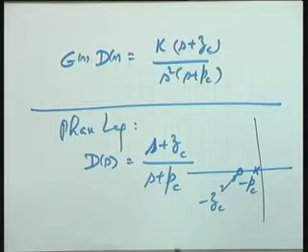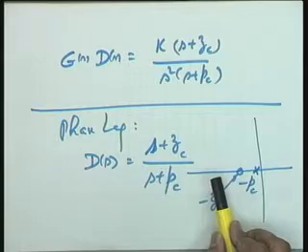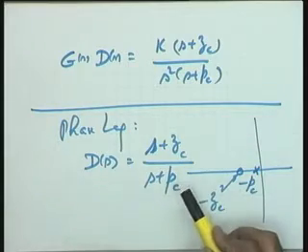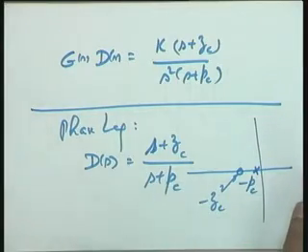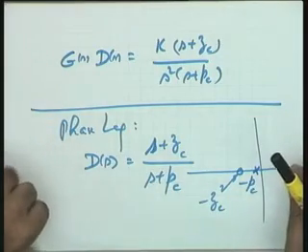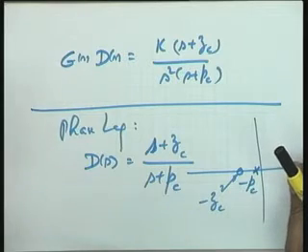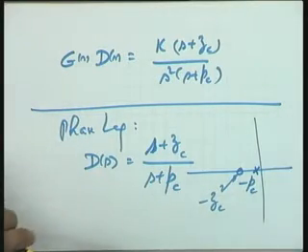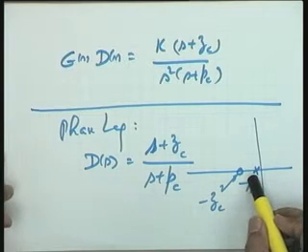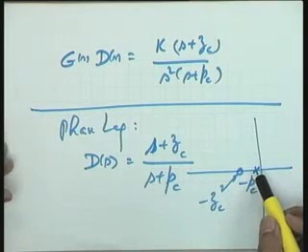Okay, so this is again a pole-zero pair, as you find, with a pole near the origin and a zero following there, and the ratio of Zc and Pc also is suitably guided, and we will see how to take this particular thing into consideration. The selection mode: how do you make the selection? Primarily you are adding a pole to the system.